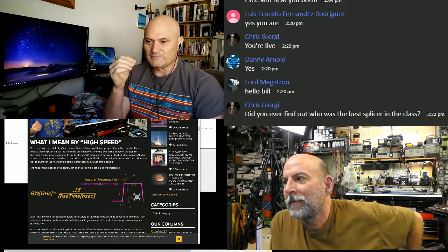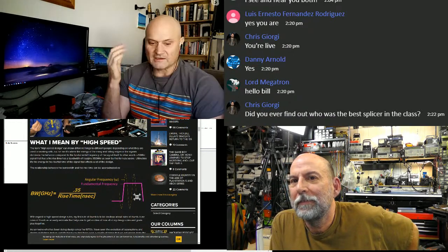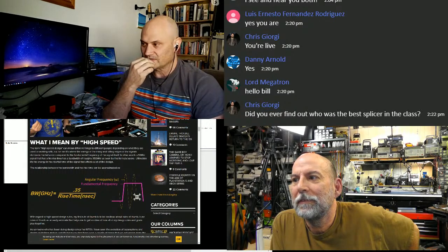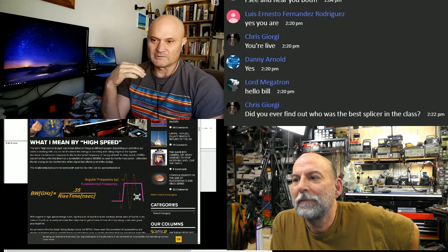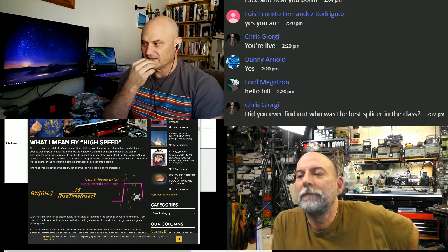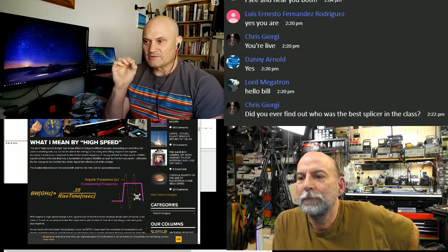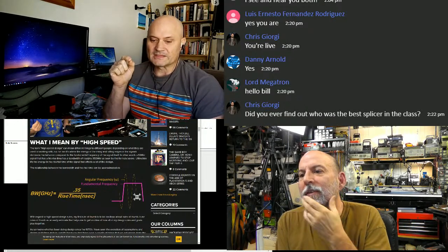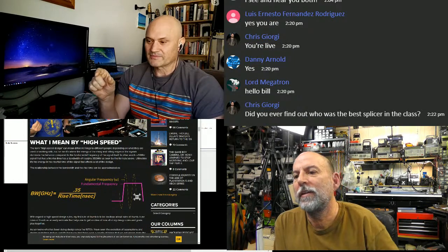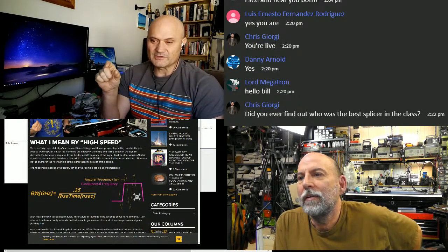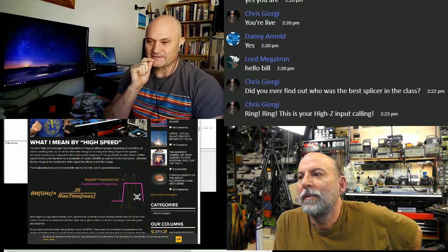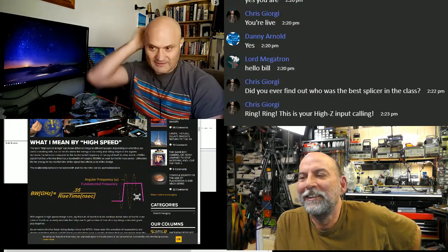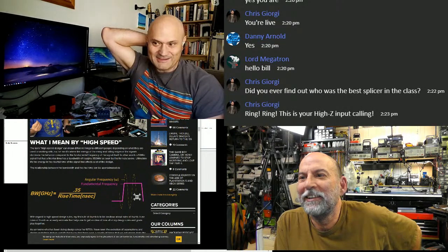But the problem now is, once we started going up around 10 megahertz and higher in our signaling, then reflection started becoming a problem. We'd get all this ringing and all that. Right. And what no one was ever able to explain to me clearly at that time was why we have series versus parallel termination. Right. And in a lot of high speed, yeah. So high speed, high Z input ringing.